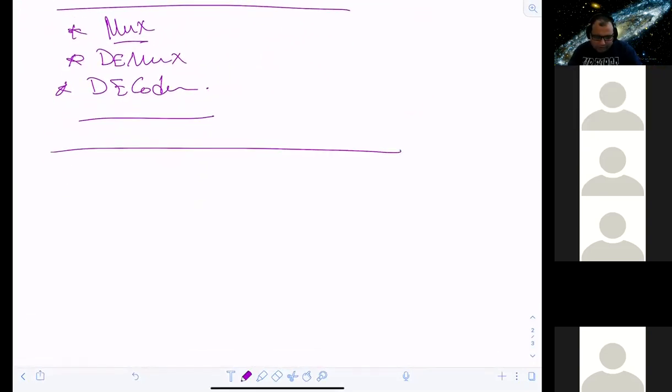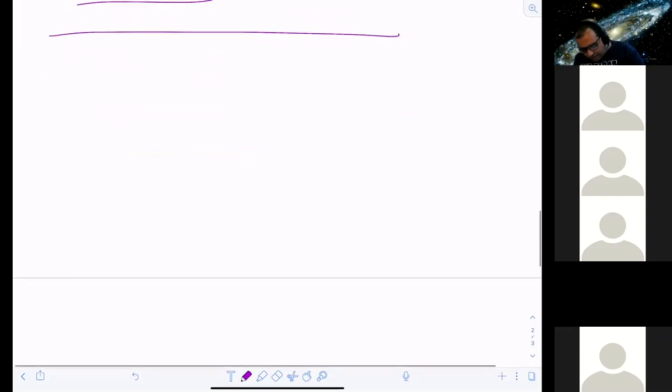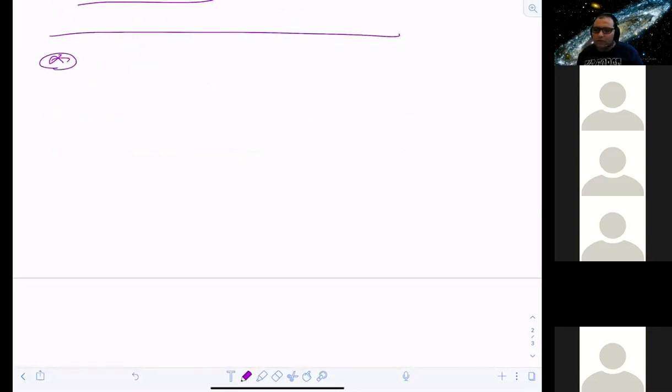So what we learned before was to build everything using gate level implementation, right? Do you guys agree? We need to see with our own eyes why gate level implementation is limited, and why we don't implement using combinational circuit elements. For instance, there was a very nice example I gave you of something called a full adder. Do you guys remember? We did it when somebody was asking for the critical path.